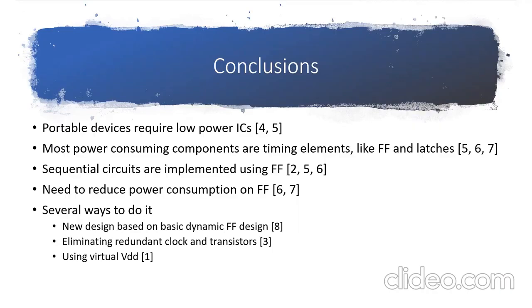Last design I explained was derived from the SR latch-based flip-flop. The design removes one NMOS transistor, which is shared, and one PMOS transistor to create virtual VDD. The new design showed some reduction in power consumption compared to the transmission gate flip-flop and SR latch-based flip-flop.